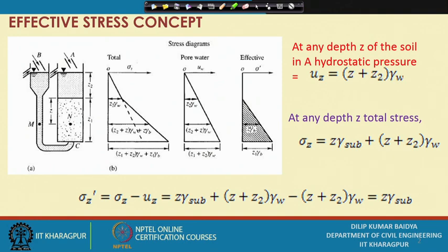So, particularly I will start with no flow conditions. Suppose this is the situation here. This is a soil mass, and water head is applied here, and from the bottom it is also connected to another tank, and the water is continuous through the soil from end A to end B. Since there is overflow from both places, if there is more water either here or here, overflow will take place and maintain the same level.